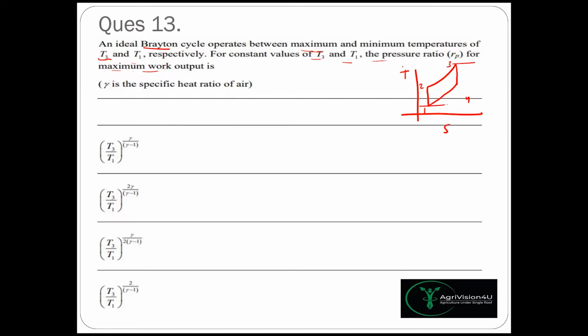different work output. Now, we know that the maximum work output we'll achieve when this behaves like an ideal heat engine or for a gas. That means when it starts behaving like a Carnot cycle, then in that case we'll achieve the maximum work output. Now, that is for maximum efficiency, right? But we need to find out the maximum work output, that is the optimum work output.